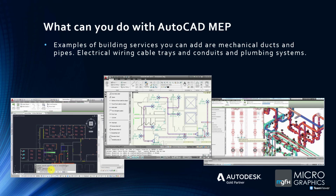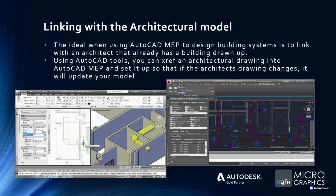Right, as you can see, it's very similar. If you stand back a bit, it's very similar to a product called Revit MEP, where you link with the architects with the Revit architecture in the model, and you add your services. Right, so this one is just based on AutoCAD. Right, talking about Revit and linking with the architectural model. If the guys are working in Revit, they can export their 3D Revit model as a DWG, and you can use that then in your environment, adding your AutoCAD MEP services.